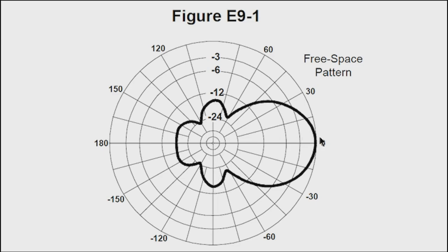So front to side, well, the front is 0 dB, so I'll start coming up. That'd be minus 24 dB there. That's 12. What are my choices there? 12, 14, 18, or 24. I'm going to say 14. It looks to me like it's closer to being 14 than it is to being 18. I would concur with that, Professor. And it's the same thing on the bottom. It's the same on both sides of the pattern there. So I'm going to say it's answer B.